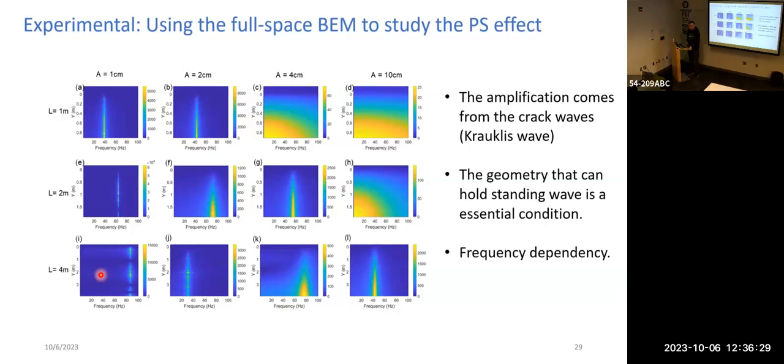What frequency is that? These have different incident waves. What are the frequencies that you're using? Oh, I did it in the frequency domain. So that is the frequency sweeping. The frequency interval is 0.2 hertz. I think 0.2 or 0.1 hertz. So this is the range of frequencies you see there? I just sweep from 0.2 to 100 hertz, and the interval is 0.2.